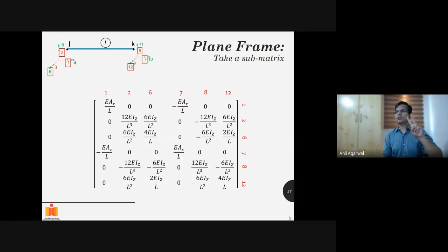Right now, we are dealing with only 2 degrees of freedom. So at each end, how much rotation is there? All other degrees of freedom have been restrained, or in fact 3 degrees of freedom you can say. At each end, what is the rotation plus axial deformation. So these are not really degrees of freedom. These are deformations, right? So rotation and axial deformation. We will translate that into the degrees of freedom in the next class, and then we will see the approximate geometric stiffness matrix that was shown in the last slide.